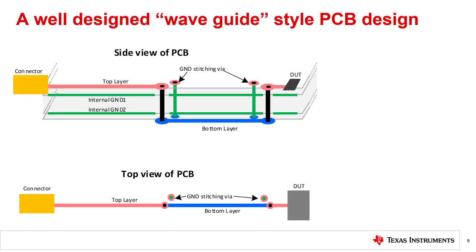Now let's look at how a signal travels across a printed circuit board when the signal transitions with vias from the top to the bottom layer. Notice that this example uses an unusual stack-up with two internal ground planes. It turns out that this is a very good stack-up for EMI. We will cover this in detail later. Now we will look at a well-designed example using vias to transition layers, then we will look at a poorly designed example.